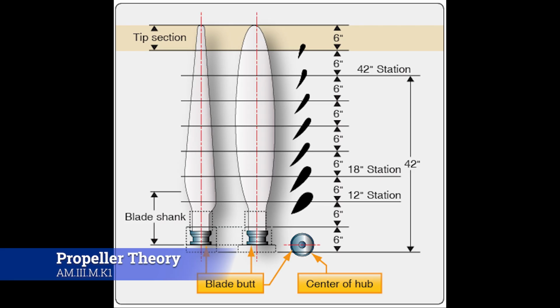Also notice that they say stations on this. Now, for maintenance purposes, a lot of the time you're going to just be inspecting the propeller and taking them on and off. You're not going to be doing a whole lot of rebuilds unless you're in a 145 that specializes in that, or you're doing NDIs and that kind of thing. For the most part, you're simply going to look at: is it leaking? Does it have any damage? Can I fix it?